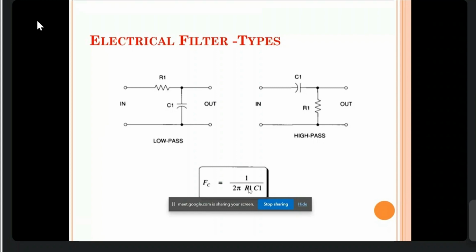So even if you go beyond 1 gigahertz, the inductor value or capacitor value will go lower than nanohenry for the inductor or nanofarad for the capacitor. For example, I want to design at 3.5 gigahertz, I am trying to design an LC filter. At 3.5 gigahertz, your component value will become beyond 1 nanohenry and 1 nanofarad.